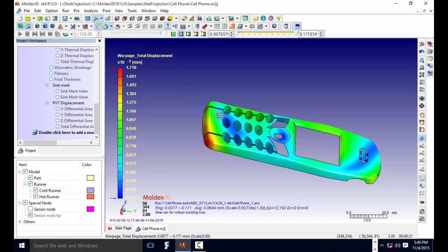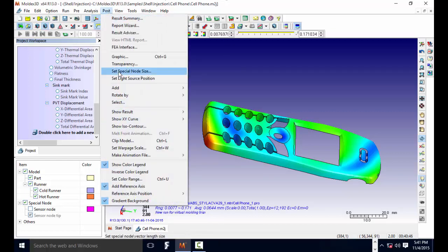But arranging the gates, riser, runner, and its typical dimensions, and going for three to four case studies, optimizing one, and then implementing it for your prototype is the key. And that is different for each and every project. You don't have a common algorithm which will fix and apply to all projects. This is very specific to projects, and that you have to understand.